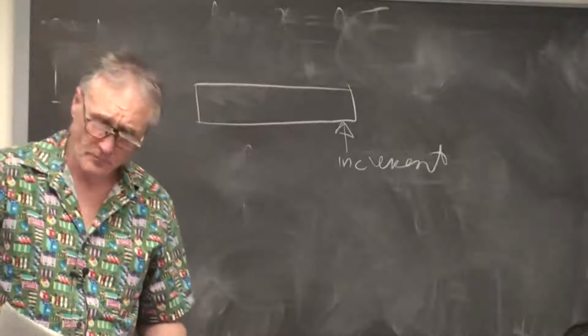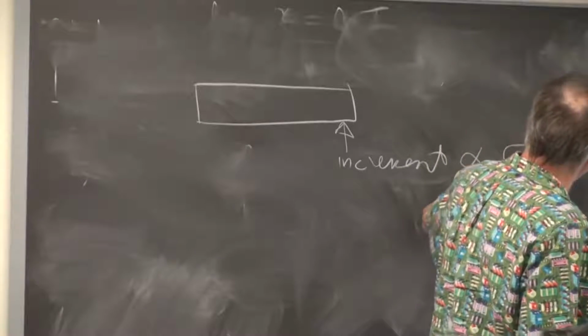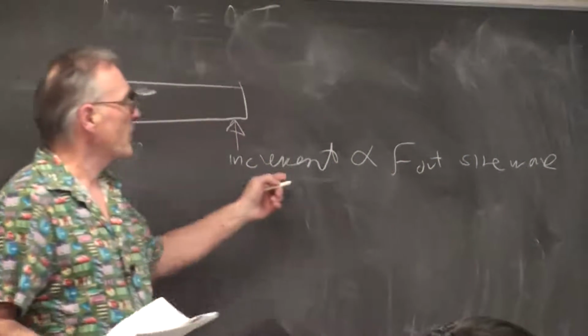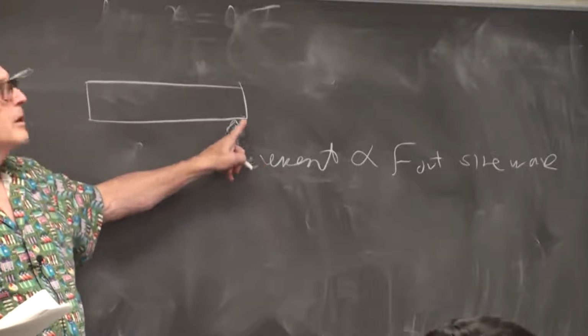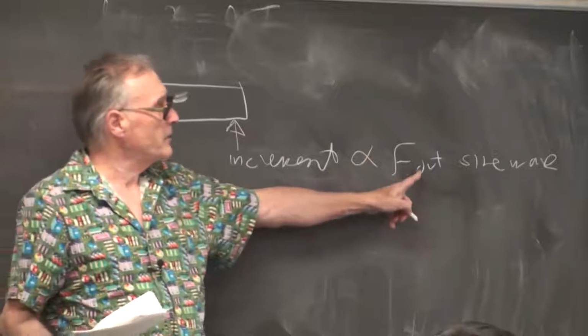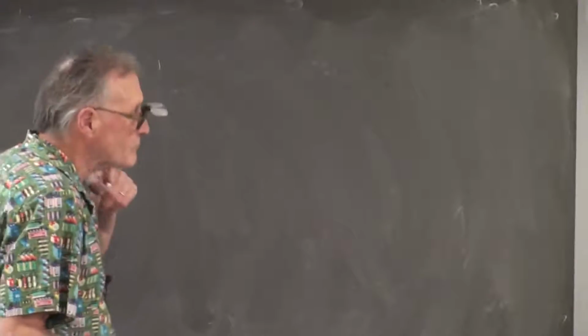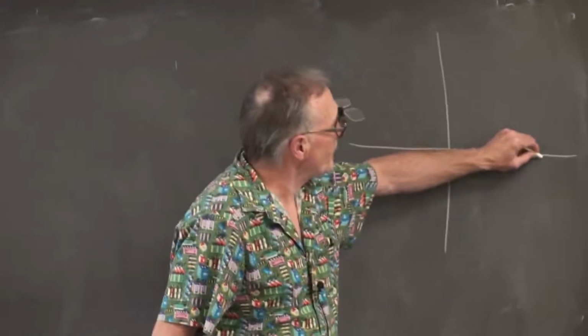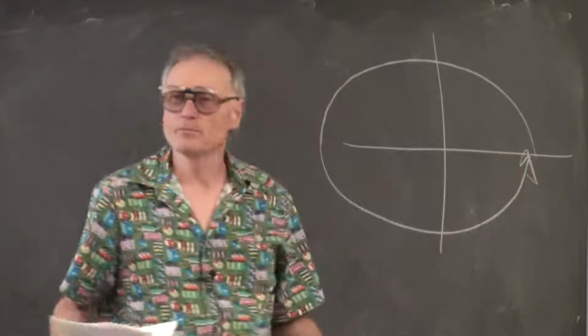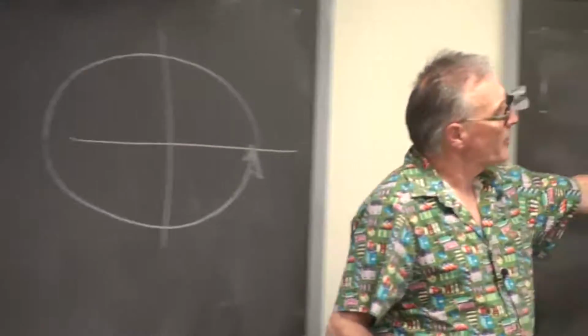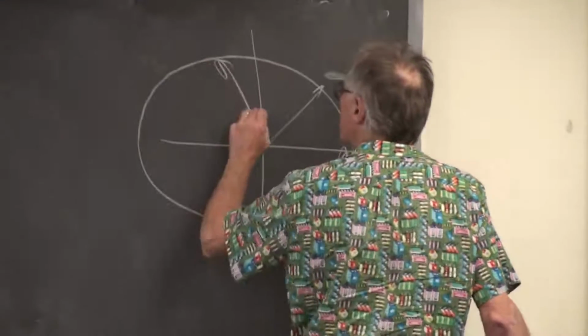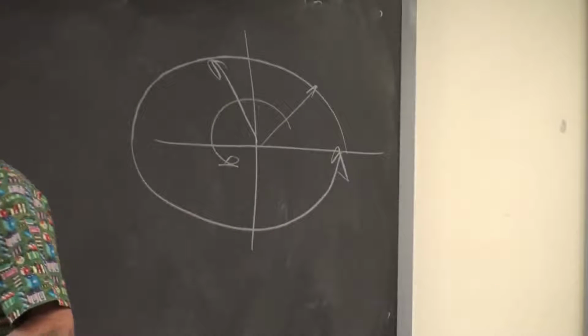So we're going to increment this variable by a fixed amount, which is going to be proportional to the frequency out that we want of the sine wave. So we're going to come up with a scheme that allows us to linearly map an increment of a variable into a sine wave of variable frequency. And once again, the central abstraction is that every time this variable overflows, it is the equivalent of wrapping a phasor 0 through 360 and back to 0. So the larger we make the increment, effectively what we're doing is speeding up the phasor as it rotates, corresponding to a higher frequency.